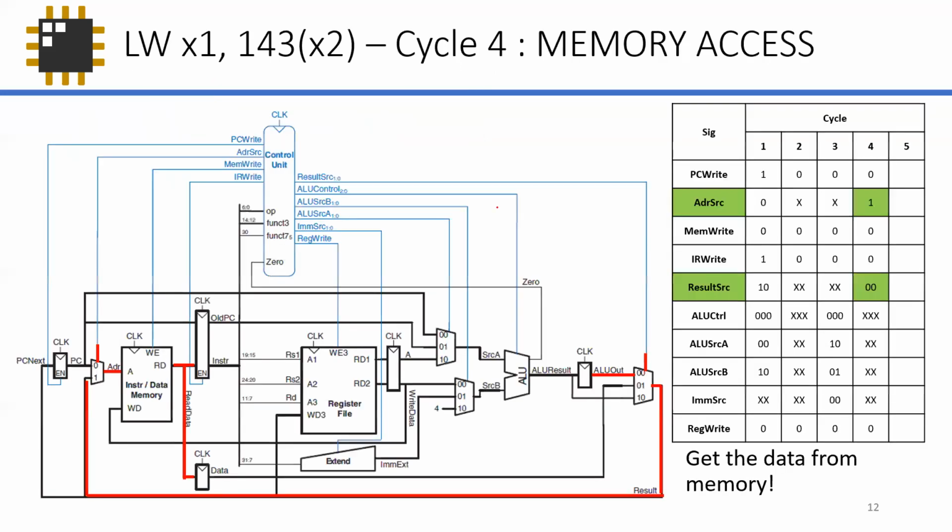So the next state is really the memory access, wherein we're going to obtain data from the memory. All right. So remember earlier in the execute state, we calculated the target address. It will be saved in the ALUR, the ALU register, which is the ALU out, which contains the target address. Then you have to feed it back into the memory right over here. Okay, because we need to load in the next cycle, right? We have to grab the data that we need, and then we're going to load it into the DMR, the data memory register down here.